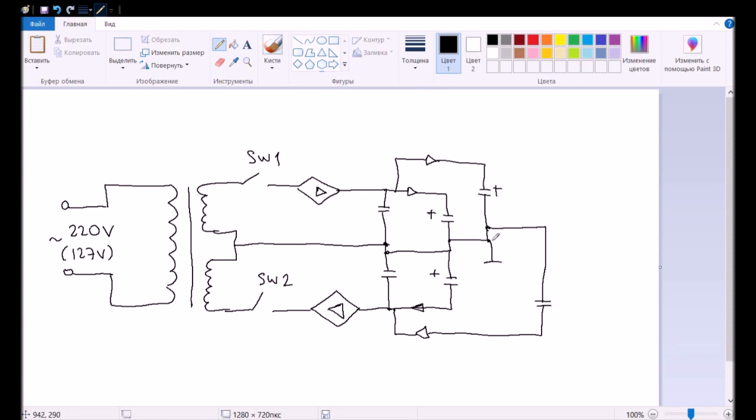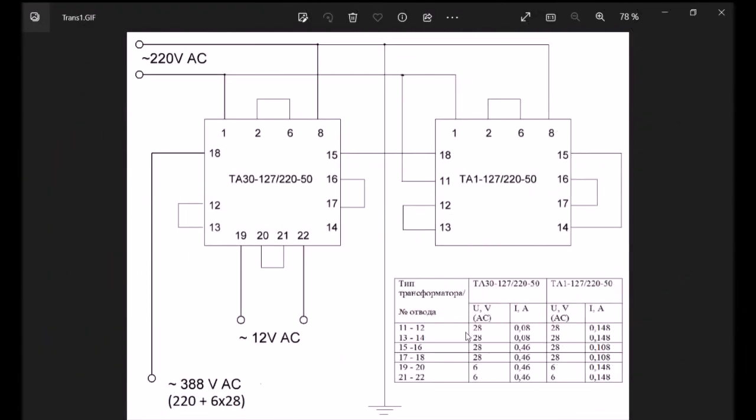So it's fully analogous to the first cascade. It also doesn't need any flattening circuits and doesn't lead to any losses. Here is the third cascade, and so on. This circuit is very handy because it is much more compact, and it has a medium point in regard to which we can measure voltage. It is very handy, and we'll show how to manage it with simple operational amplifiers or comparators.